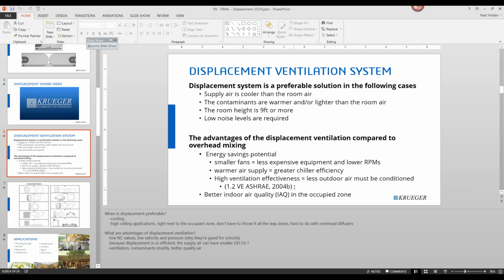You can actually, when you're coming down in the ductwork, I can't tell you exactly where they need to be located, but since these are actually in the room, if you have ductwork coming down, a lot of times they'll locate a measuring station directly at the inlet of the displacement device. So you have the duct coming down, then a measuring station, and then the displacement unit.